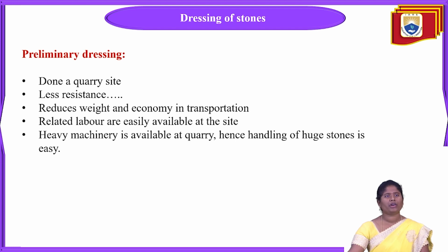Why does this dressing of stones have to be done at the site? It will reduce the weight and also the economy, meaning the transportation cost, everything will be reduced, because by doing the dressing of stones at the quarrying site, it will be very easy to reduce the cost and also the weight of the transportation.